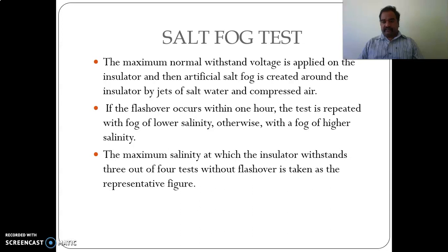And since it is just like salt fog and you have applied your normal withstand voltage onto the insulator, you are supposed to wait for 1 hour. If the flashover occurs within 1 hour of application of your voltage, which means that during the entire 1 hour your insulator is experiencing the withstand voltage. During this procedure, if there is a flashover, then immediately they will reduce the salinity, the salt level in the fog. And if there is no flashover, they will immediately move on to the next, higher level of salinity.